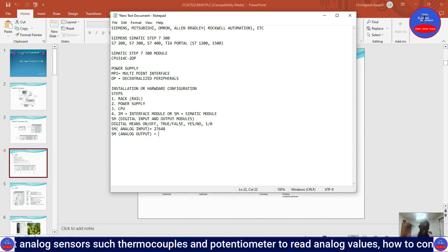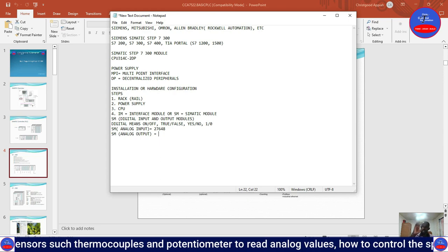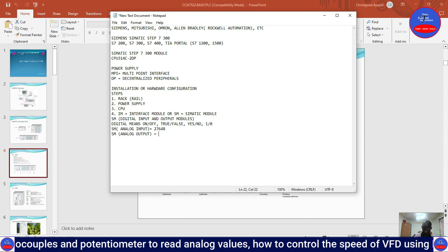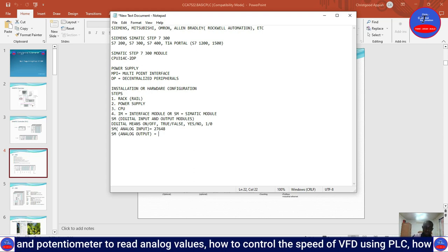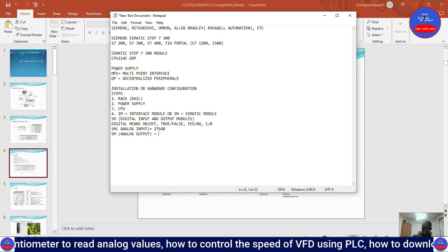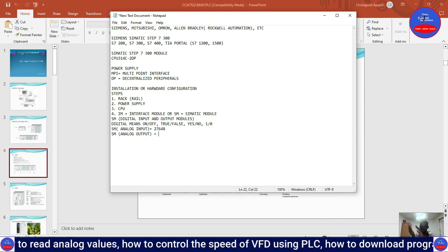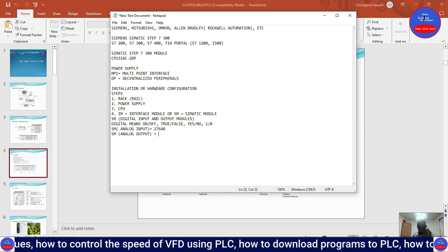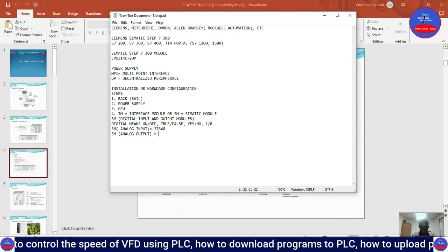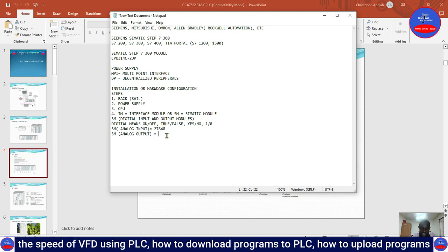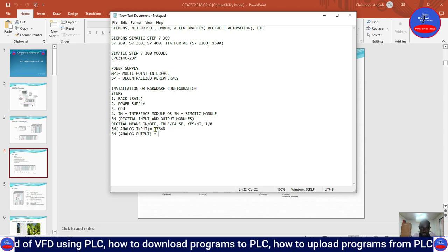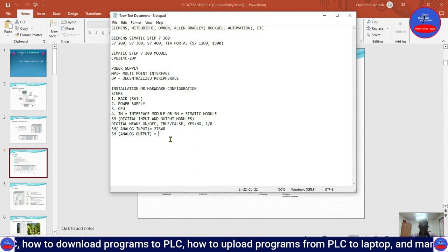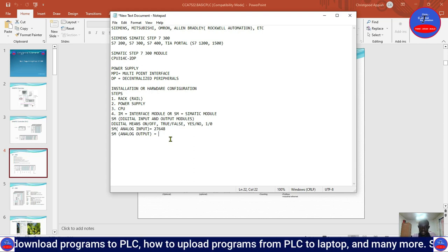Or you want to open a valve to some percentage, let's say 20%. You enter 20% on the HMI or the laptop or the computer, and then that particular valve will also open the same degree or percentage that you want. So when you input that value there, it will be converted to an integer value and sent to the valve. So that is the analog.